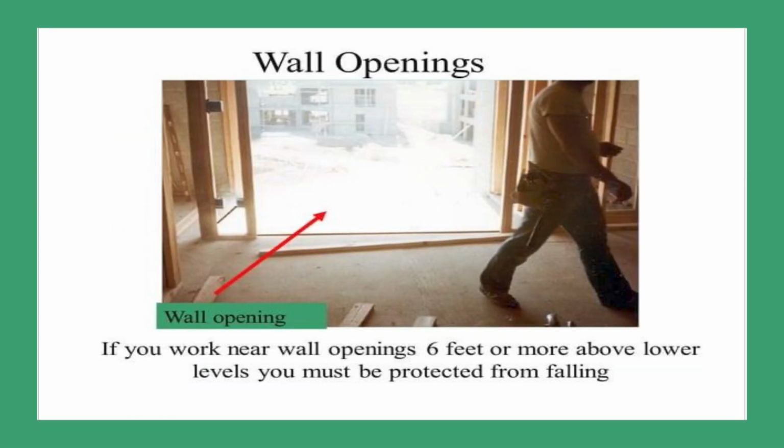Wall opening. If you work near a wall opening 6 feet or more above the lower level, you must be protected from falling by a personal fall arrest system. Summary: if you can fall from more than 6 feet in height, you must be protected.